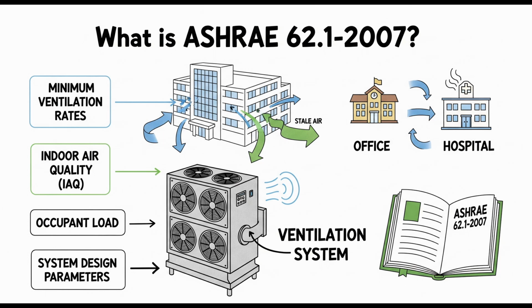Exactly. Then comes system startup. Before you hand the building over, you have to test and commission this system. What does that involve? Critically, testing and balancing. An independent agency usually comes in to measure the actual airflow at diffusers and intakes to verify it matches the design rates, making sure the ventilation rates are all being delivered as planned.